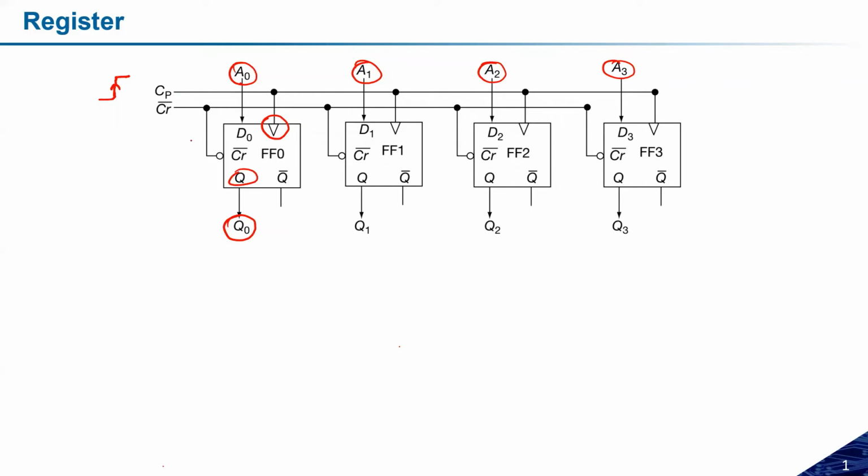If I have connected more registers, 8 flip-flops, then we can make it an 8-bit register. As of now, because I have only 4 flip-flops connected, whatever diagram we are seeing here is nothing but a 4-bit register, and it can store 4-bit data. This is the simple working. Just understand this slide, and later on you will be able to understand all the circuits that I am going to project.